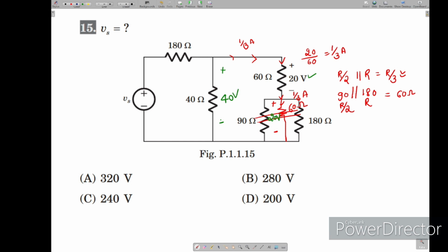So we should know the voltage divider rule. What it says is we have a voltage source Vs and two resistors like this, R1 and R2. I will take current I. Across R2 the voltage V2 is nothing but Vs times R2 divided by R1 plus R2. Same way we will find across this also.